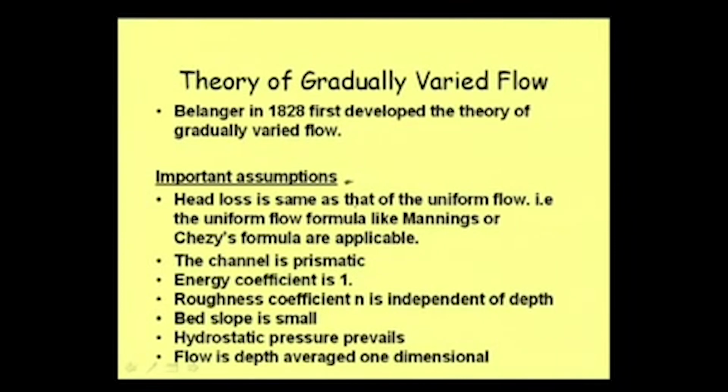That is why I am giving some of the important assumptions that are very obvious, and of course, apart from these, some smaller assumptions are always there which we are not mentioning here. The first assumption, which you can see on the slide, is that the head loss is the same as that of the uniform flow. That is, the uniform flow formulas like Manning's or Chezy's formula are applicable. Already we have discussed that Manning's formula and Chezy's formula are all uniform flow formulas.